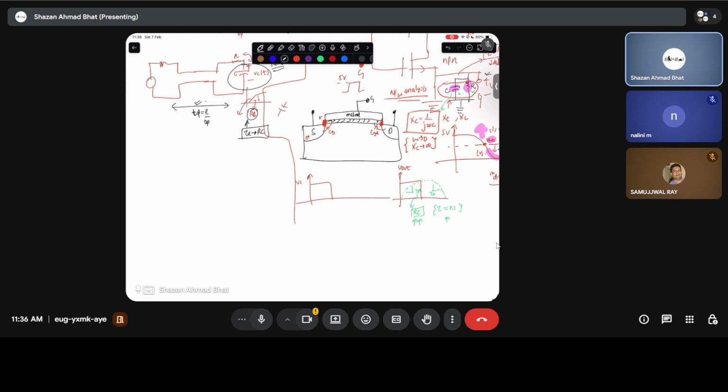And now, if we, for example, have a sort of a network, something like this, then we can simply apply KVL or KCL in order to analyze basically the voltages and the currents. And you know that the current across the capacitor can be given by C dVc divided by dt, which is basically the current across the capacitor. If it would have been an inductor, you could write the voltage across the inductor is basically L dIL over dt, which is basically the rate of change of current through the inductor. But here we are talking about a capacitive load.